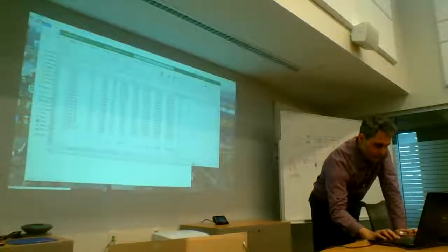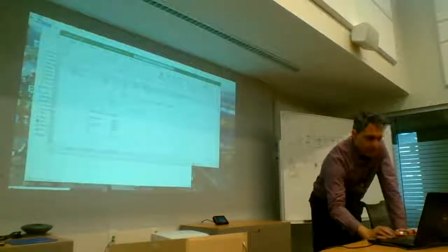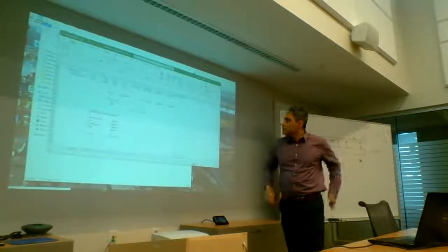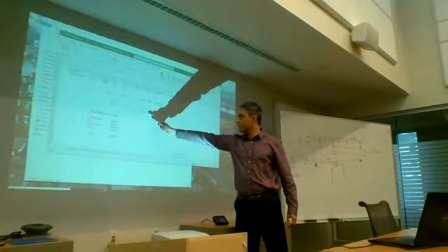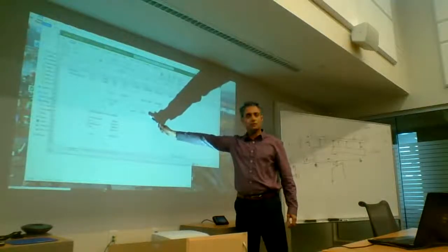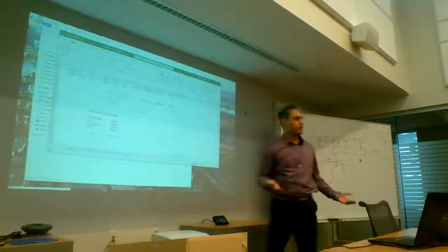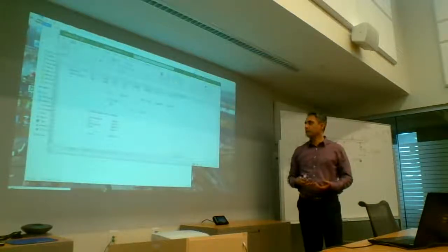And what I wanted to show you here is I've got the total weight, and alpha, beta, gammas are all calculated here. From this simplified analysis, I got a period of 0.3987. And when I just do everything in CSI Bridge, I got 0.406. So they're very, very close.